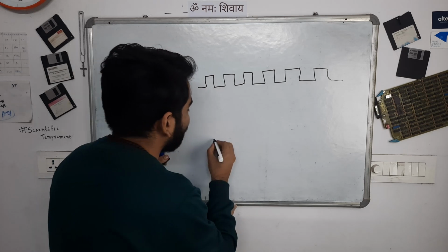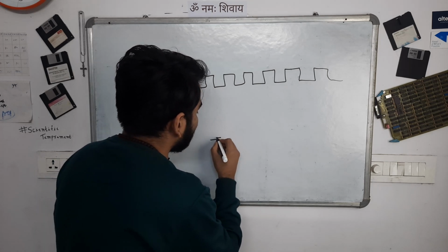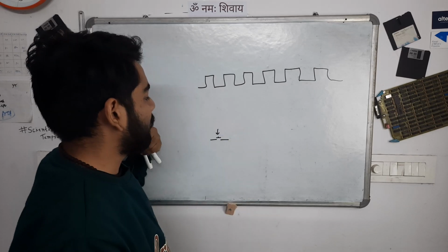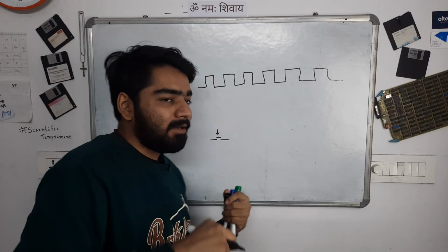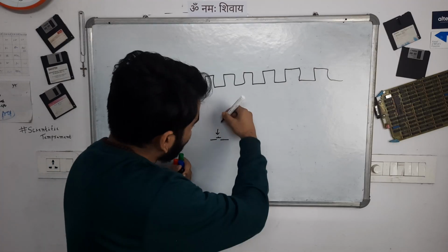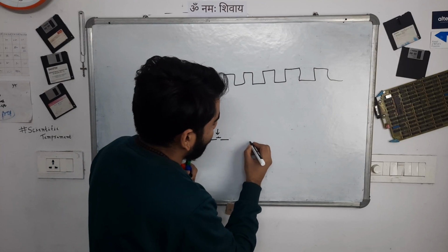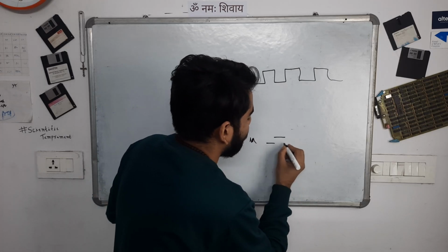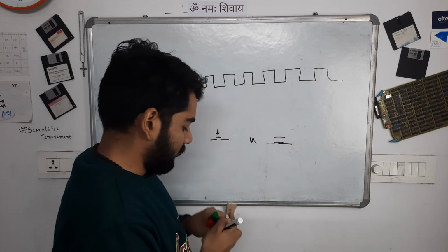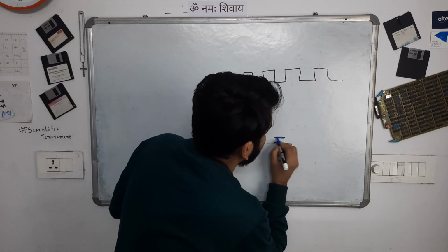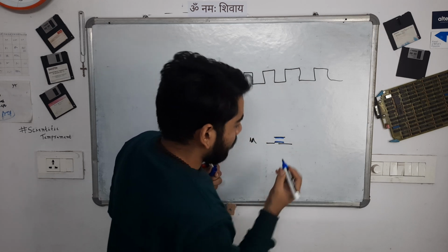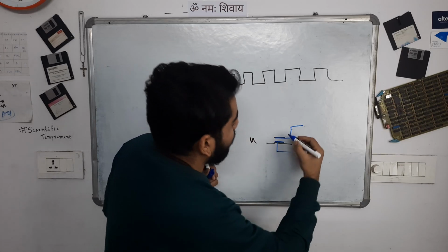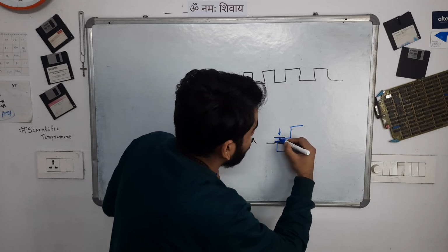The second thing is that the push button that I'm pushing over here, these kinds of push buttons do not give definite ones and definite zeros at the time of pushing. What I mean by that is, whenever you push, the button sort of bounces. What is a button? Basically a button is something like this. You have one contact right here and one contact right here. This is wired to one of the terminals, this is wired to another of the terminals, and when you push the button, it basically comes in contact.